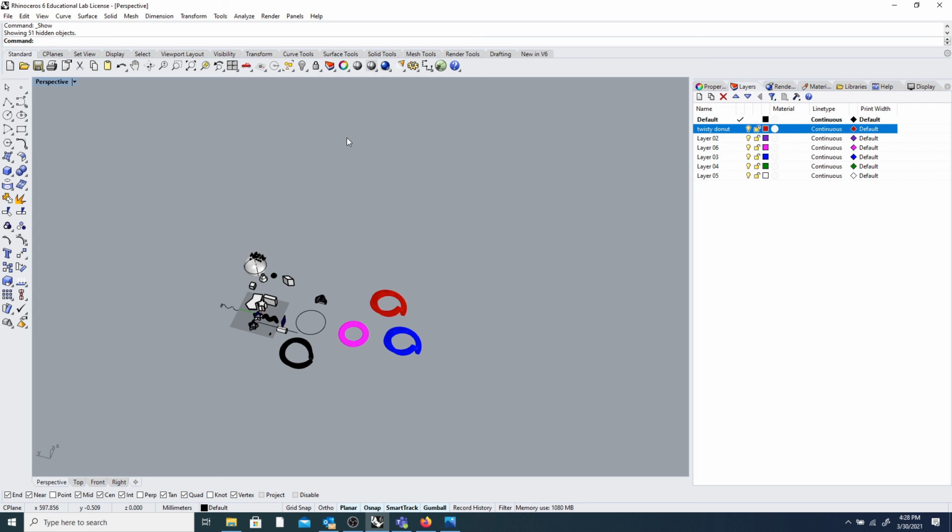One really practical reason why you may want to be able to hide your objects, maybe one by one, or only be working on one at a time, would be the limitations of your computer. So your graphics processor has to render all this stuff on screen. So if you have a ton of really complex, really heavy shapes, so they've got a lot of work done to them, it could really tax your computer and slow things down. So hiding those speeds it right up. It's not being rendered anymore, so it's not in your workspace.